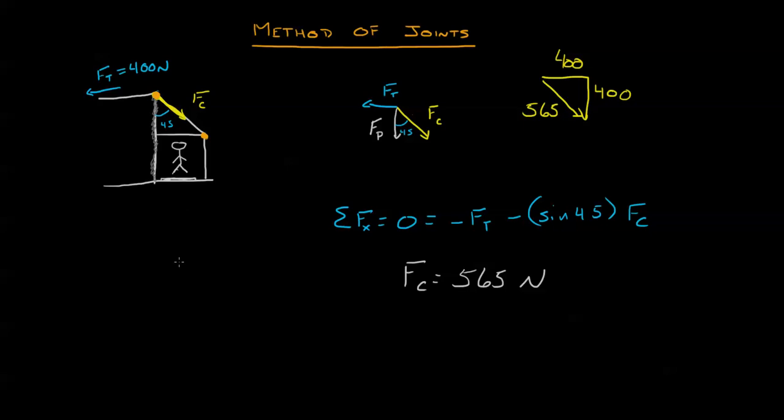Now we know that the force of the cable goes that way, and we'll call it the force of the support. We know it's going to be pushing in there, right? The force of the support, and then we'll have something below this force right here. We'll call it force lower. Now, you already know how to do all this stuff, but I want you to see that this is simply by looking at one joint and identifying all the forces, or summing all the forces around that joint to 0. We can use the same in trusses.